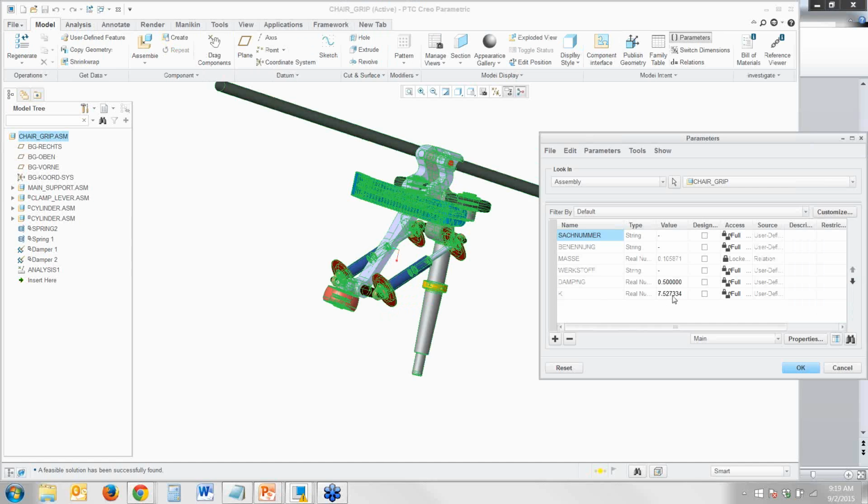And so what it just told me here is initially you had a K value of 10. You can use a spring that's 25% less stiff than what you initially had and achieve your performance target. And so again, this is a case where I can go back to my boss with the dollar savings and say, hey, we can buy a cheaper spring and still achieve our performance target of 2,500 newtons of gripping force on that rope.